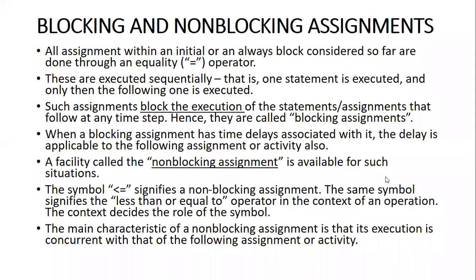Now we'll see what blocking and non-blocking assignments are. So far, all assignments within an initial or always block have been done with the equality operator. We have used an equal to sign for all the assignments within the initial or always block. If you use an equal to sign within an always block, it is understood that the statements are executed sequentially, one after the other.